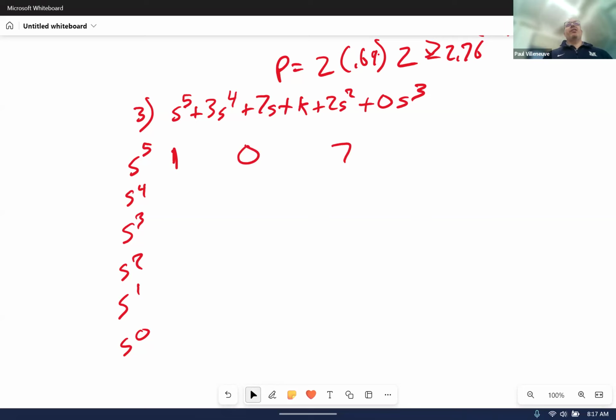If a term vanishes, or if you have a negative term, the system can't be stable. So you didn't have to do anything in this one other than to say the system can never be stable because you don't have an s cubed term. You didn't need to. You had to do no work. You could have just written down, since there's no s cubed term, there's no value of K.